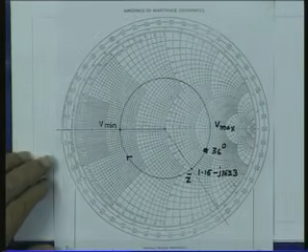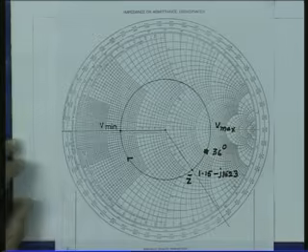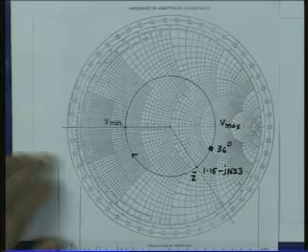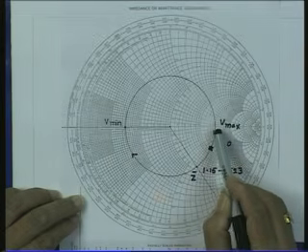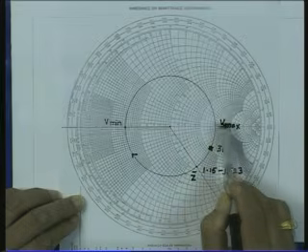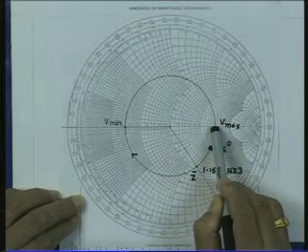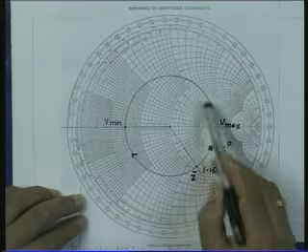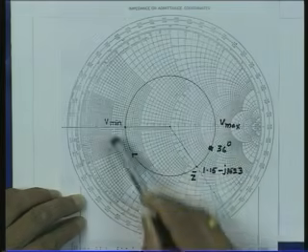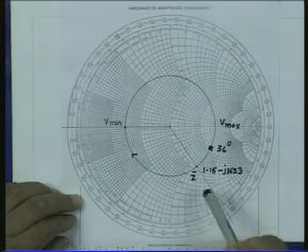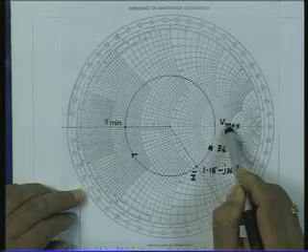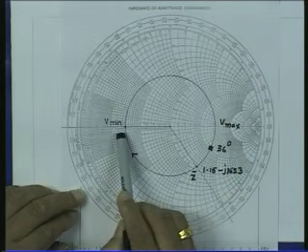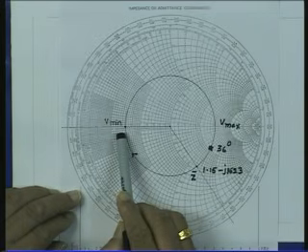So, we take the Smith chart, and since we know the VSWR, first we draw the VSWR circle on the Smith chart. We take the normalized R equal to 3 point on the horizontal axis on the right side of the center of the Smith chart and draw a circle passing through it. This circle is the VSWR 3 circle. The rightmost point represents the location of the voltage maximum, and the leftmost point on this circle shows the location of the voltage minimum.